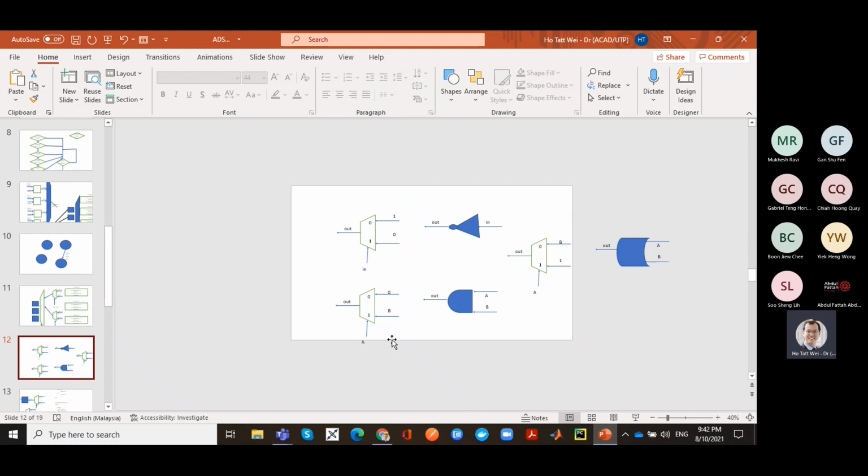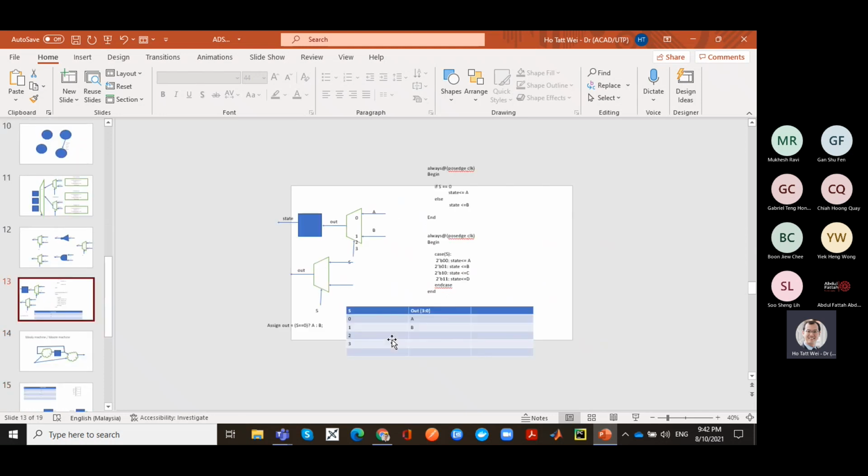And the multiplexer is interesting because it's a very natural way to think about if and else or case statements, right? The if and else condition is the selector here, and then you're setting some kind of output based on the condition. So it maps very nicely. You can look at the circuit and straight away write Verilog code with your eyes kind of closed. So that's the interesting idea about using a multiplexer to describe circuits.